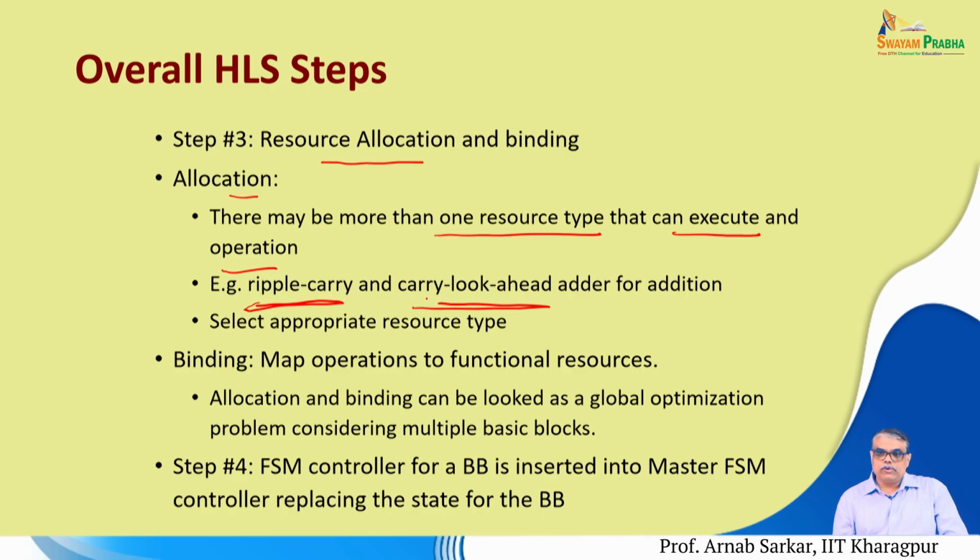For example, we could say that a few addition operations will be performed in the ripple carry type adders, and certain other addition operations within the application will be performed in the carry look ahead type adders. Now, when we have decided which operations will be done in which types of hardware resources, we will do binding.